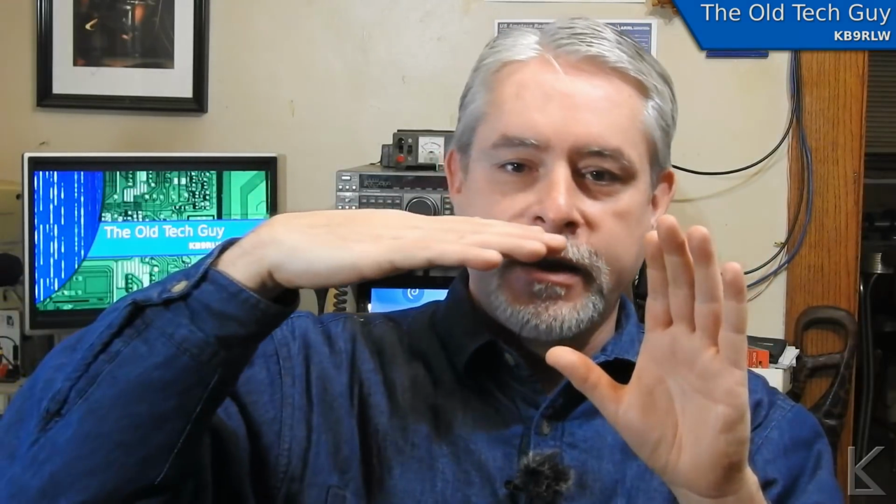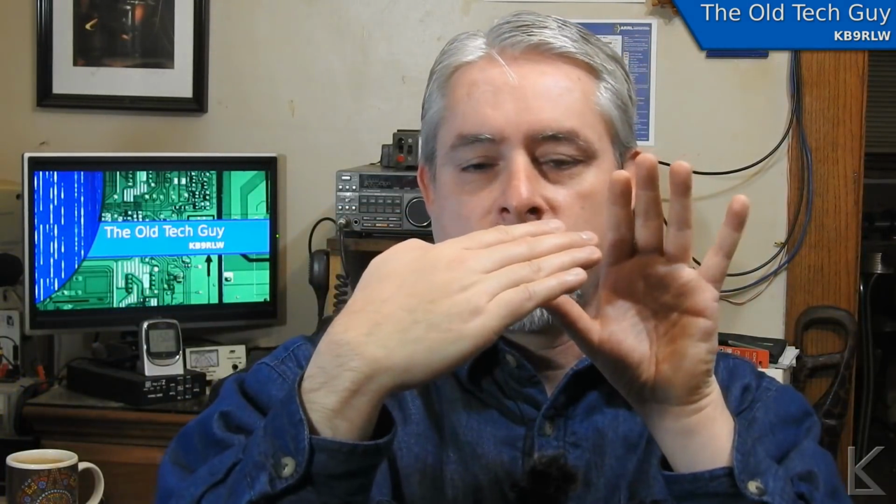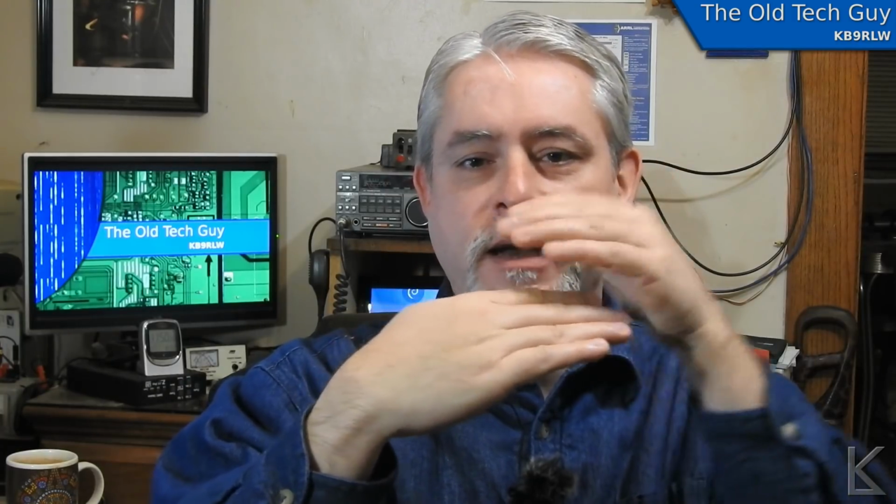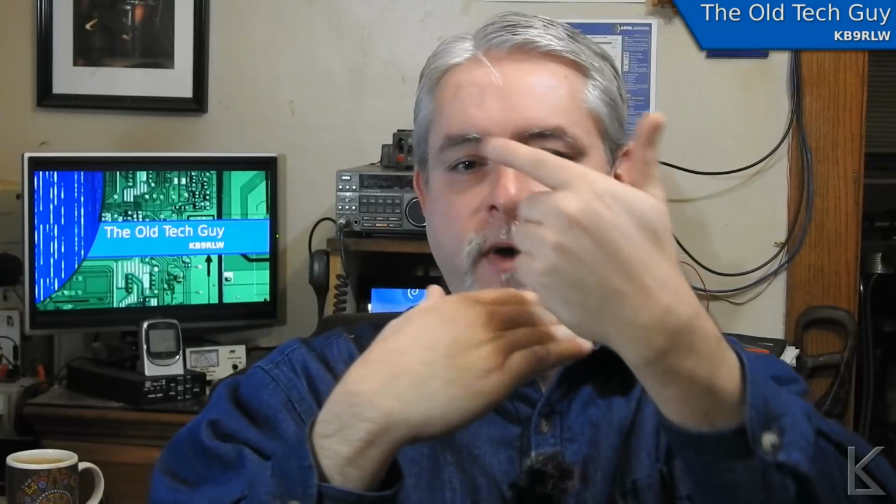internal geometry. You know, imagine taking a cube, right, and putting a playing card into that cube. Visually, you don't care about the part of the card that's inside the cube. Right? There's a wall of the cube there, so you just render the outside stuff. But if you're taking that geometry and trying to slice it for a 3D printer or a CNC machine, the slicing software is going to see that internal geometry, and it's going to try to figure out what to do with it. And you can get by with that in some cases, but in other cases it just makes your printer do all kinds of unnecessary moves, and it can lead to messy objects, messy prints, and other issues.